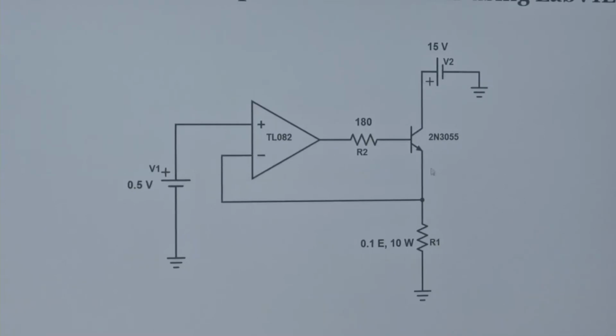The amount of current flowing through and the voltage across collector and emitter together give a power across the transistor that will be too high, which causes the transistor to heat. So, the higher the current and the higher the voltage drop, the higher the power, and the higher the temperature generated on top of it.